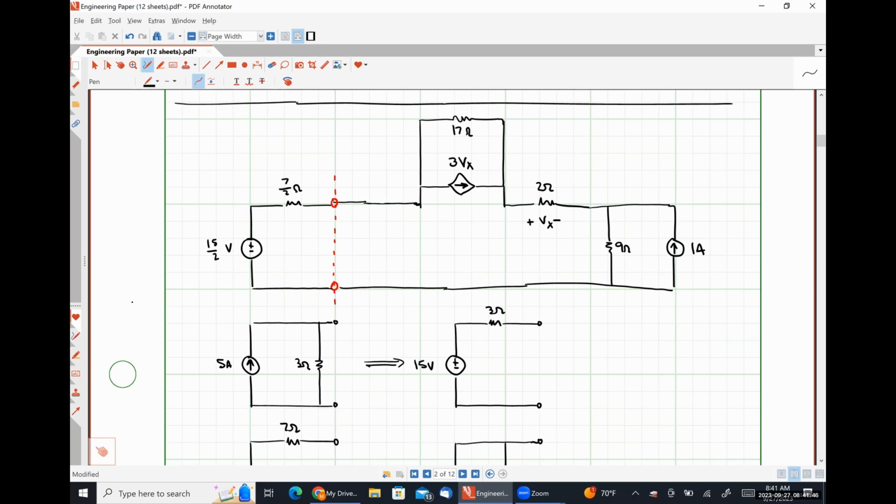So if we had the resistor in parallel with a voltage source, the voltage drop across the resistor would be fixed to be whatever the source voltage is. And the current would also be fixed because it would just be whatever the source voltage is divided by the resistor value. So we're not doing any sort of transformation because everything is literally always a constant, right? So that's why it has to be the other way around.